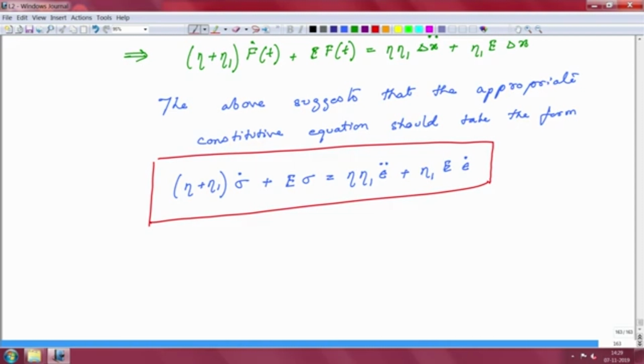So, if a real fluid exists, it is likely that it will have many different especially in cases where polymers, where there is polydispersity and etc., the polymers will not behave in a manner that you can represent them by a single E or a single eta. So, a realistic model should have many different springs and dashpots together probably, and hence we should now look towards